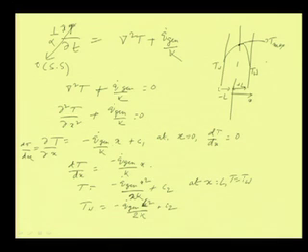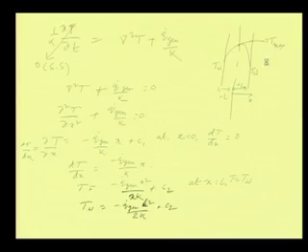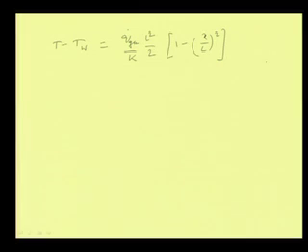Okay. And these are the wall temperatures at x. The value of T max we can find by putting x equal to 0. At x equal to 0, that is equal to T max. So, you can say that T max is equal to Tw plus q dot gen by k into L square by 2. So, this happens to be the maximum temperature in this case.